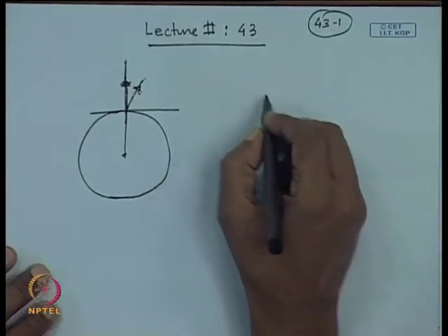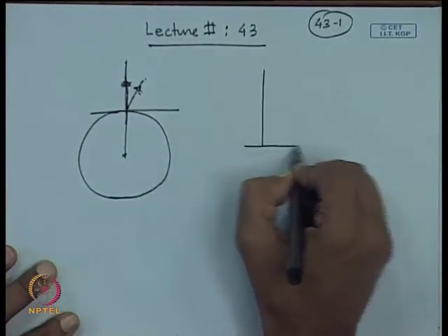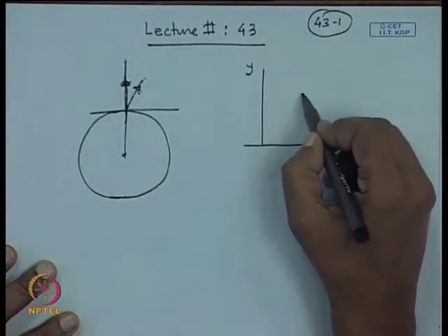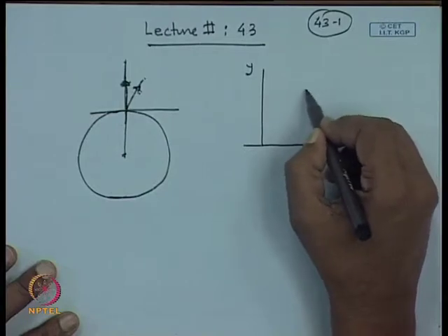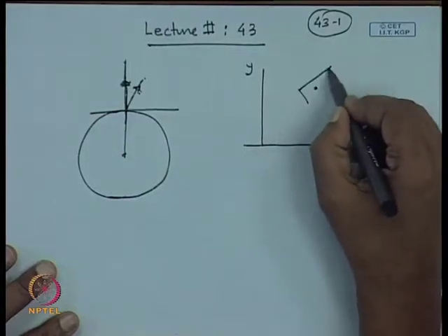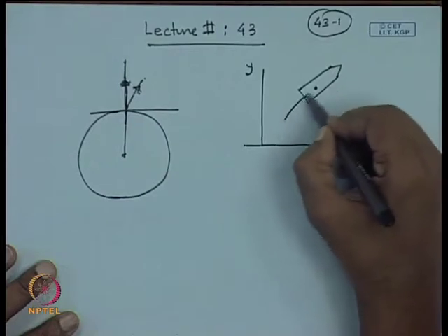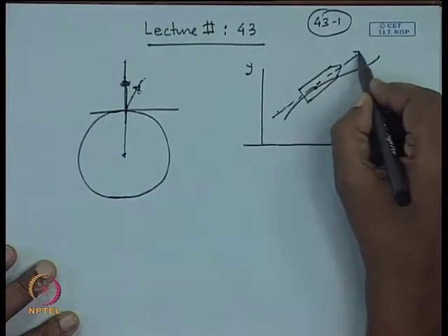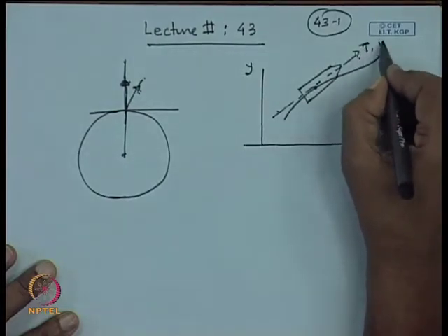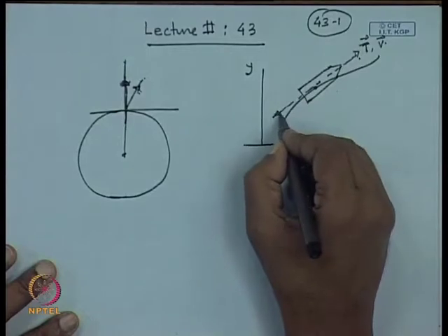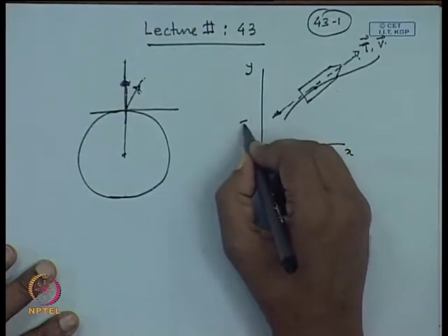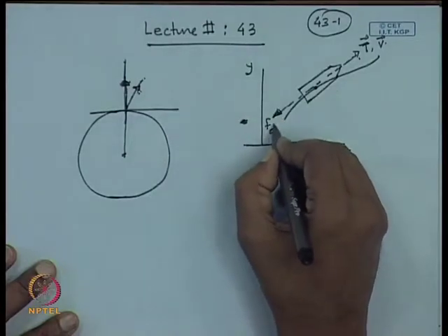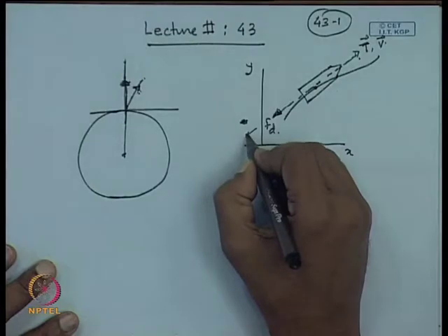So, in that context we had the x and y reference chosen, and anywhere we depicted the rocket motion along a certain trajectory. Tangent to the trajectory, along this, we have the thrust and the v vector, both acting here. In this direction we showed the drag. So, F drag and F gravity also we showed here in this direction.